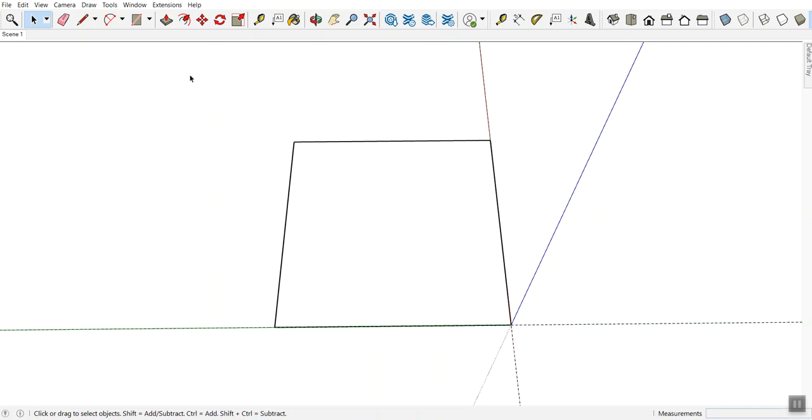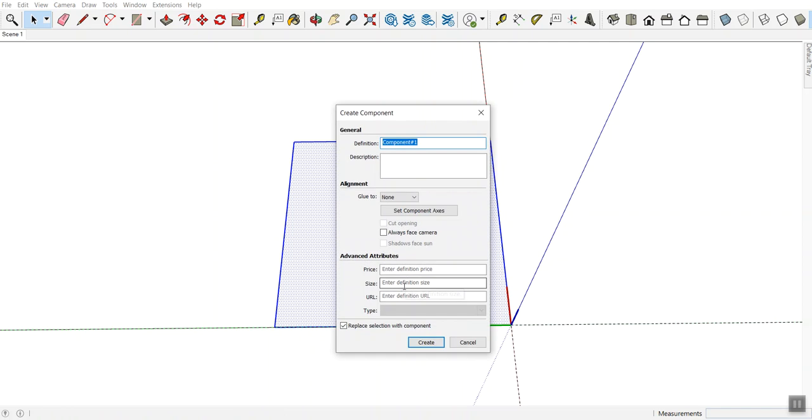So my cursor is up here anywhere. I'm going to click and I'm going to drag it. So when I did that, I selected this. It's not going to select the dotted lines or any of this blue stuff because that's basically background stuff. It's only selecting what you drew. And again, if you notice those little dots are in there, so I'm inside it somewhere. The outside is blue, blue, blue, and blue. I'm going to right click, and this is where I'm going to say make a component.